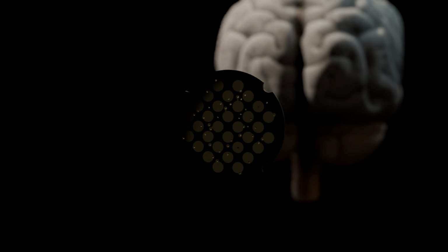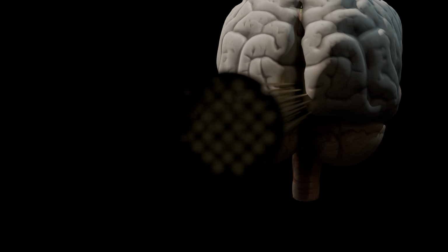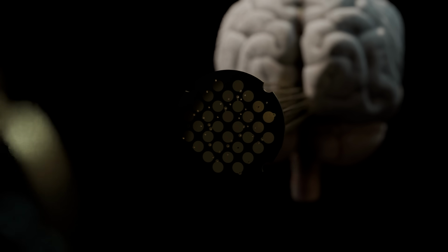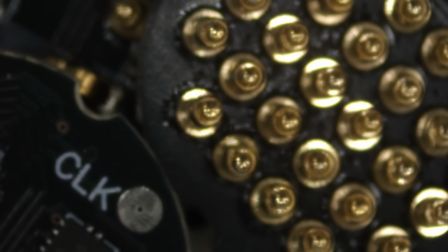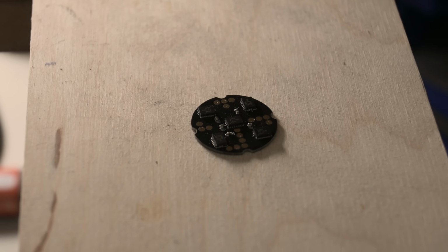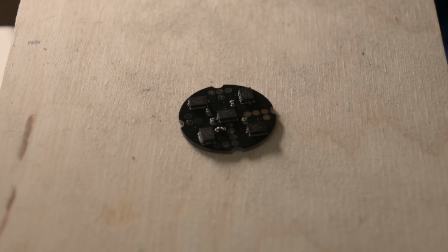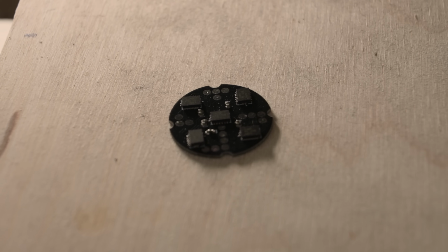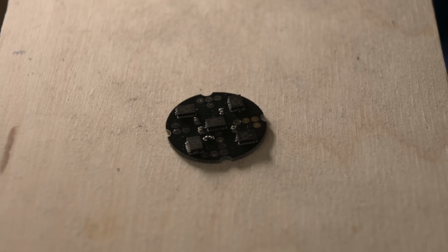For this version, I set the neural matrix size to have 32 electrodes. This number was relatively arbitrary and could be anything. We assume everything on the brain side is taken care of already, and all of the electrodes are connected to a base plate PCB. Now on the MindLink side, we have a new layer. This will have spring pogo pins to match the pads on the brain baseplate. Of course, at this point, it is probably clear that the ATmega32U2 microcontroller would not have enough pins to properly accept all 32 of these inputs.